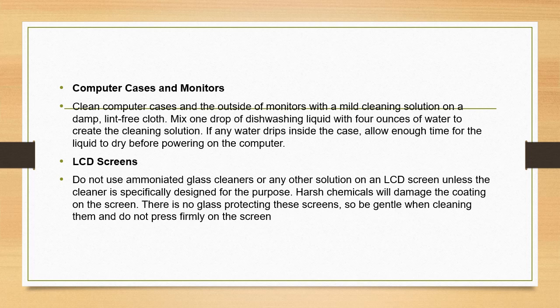LCD screen. Do not use ammoniated glass cleaners or any other solution on an LCD unless the cleaner is specifically designed for the purpose. Harsh chemicals will damage the coating on the screen. There is no glass protecting this screen, so be gentle while cleaning them and do not press firmly on the screen.